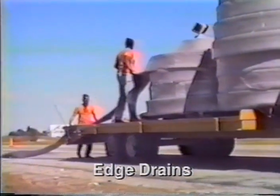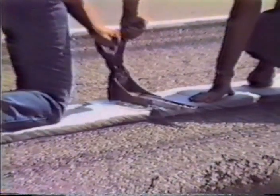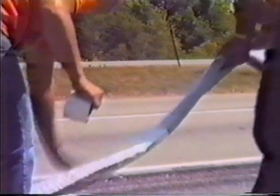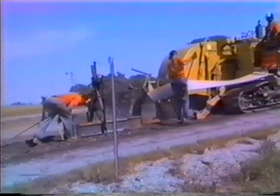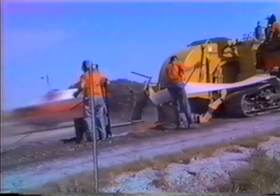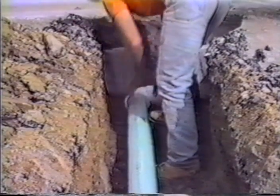Here, a prefabricated geocomposite edge drain is being positioned to carry water from the base course of the highway. Good connections with overlapped geotextile splices are critical to prevent soil infiltration. A continuous trenching machine followed by a traveling boot device allows the drainage material to be placed to the correct depth and slope. The narrow trench is backfilled and compacted, and the drain is then tied into the collector drainage system.